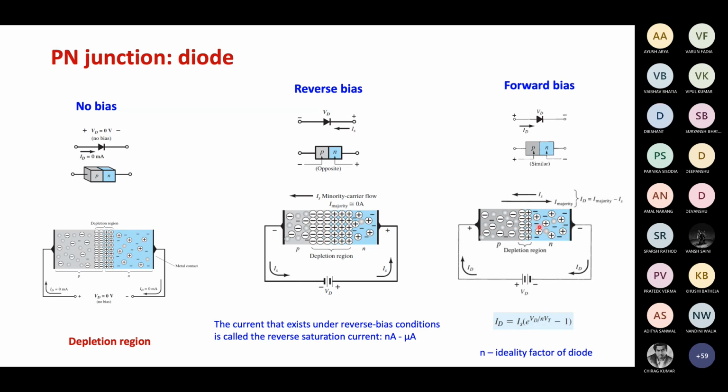Now the electron cloud is there around these atoms, which means that effectively they will be neutralized. If there are free electrons around these static ions, a cloud of electrons is there, and that is there because of the forward bias, because in the forward bias we apply a negative voltage which pushes electrons to this side. So it basically pushes the electron cloud to these atoms, and so effectively they become neutralized.